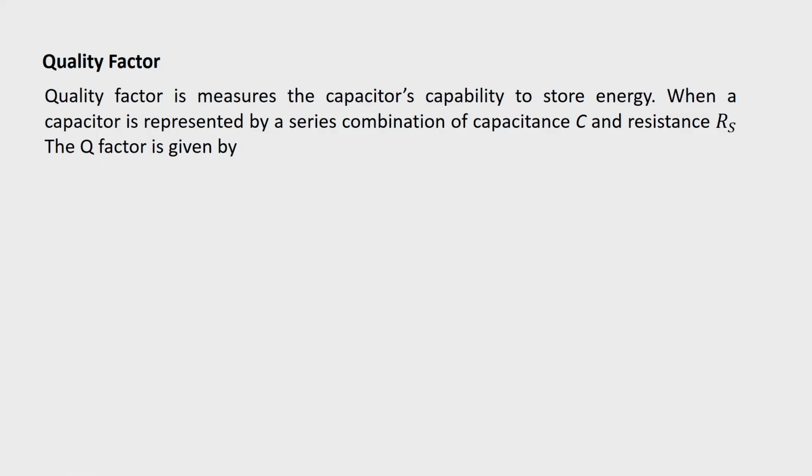Quality factor, as already mentioned, is a measure of a capacitor's capability to store energy, and when a capacitor is represented by a series combination of capacitance C and a series resistance Rs, we can write the quality factor Q to be equal to 1 by 2 pi f C Rs. So, smaller the value of capacitance, higher will be the value of Q, and higher will be the capacitor's capacity to store energy.